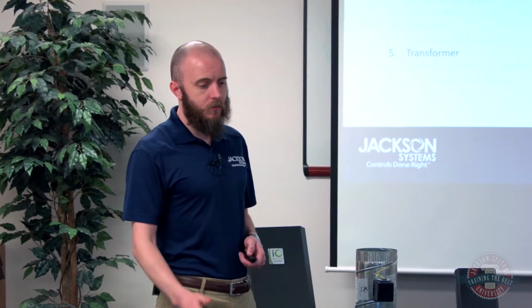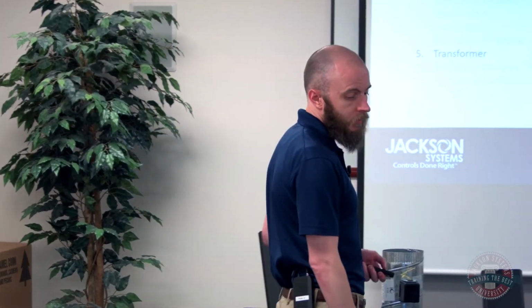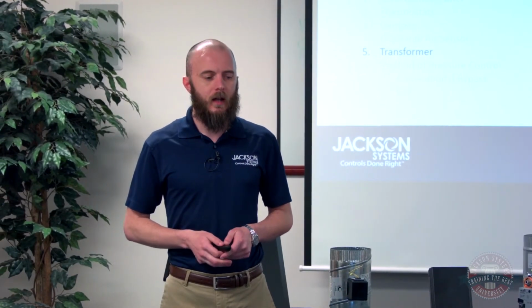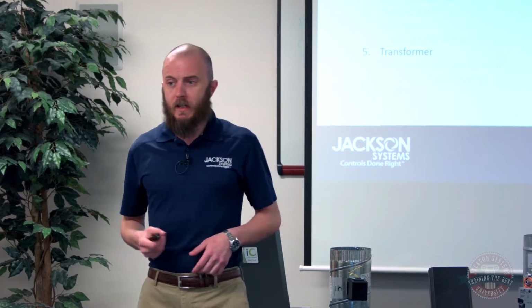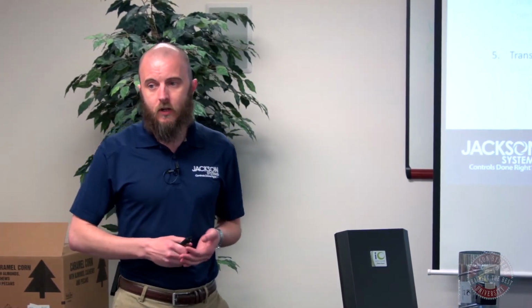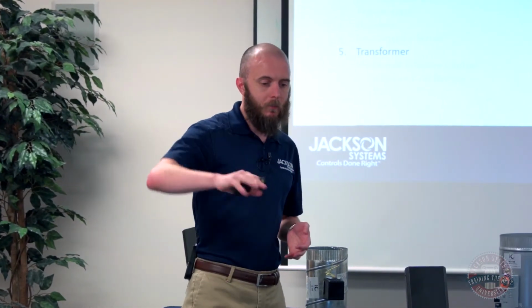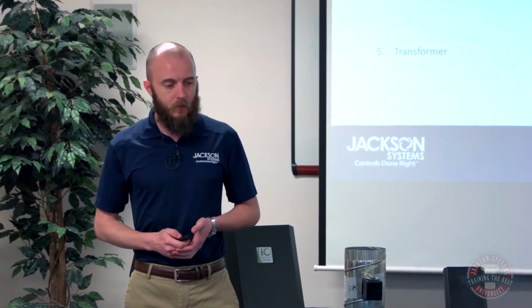Transformer for the system, we always recommend installing a separate transformer for your zone system. Don't use the equipment transformer. This can prevent a lot of hassles and a lot of issues down the line, mainly because when you install a new transformer, you know what the VA rating of that transformer is, and you know exactly how much load you're putting on it. You don't have to worry about what else may be going on inside that piece of equipment. And then lastly, some method of pressure control.